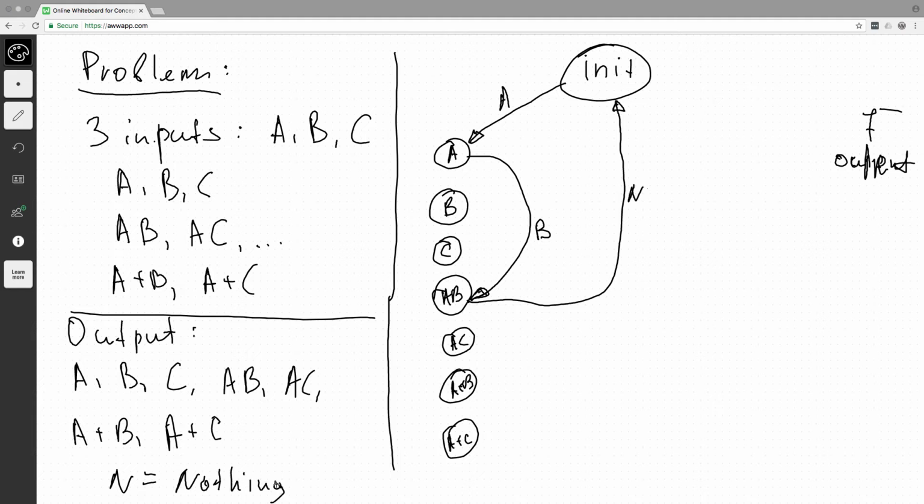Nothing is pressed. So once we move to state AB, when nothing is pressed, which means after we release the key of B, our input keyboard is in the state that no key is pressed. When no key is pressed, we will move on to the initialization state.